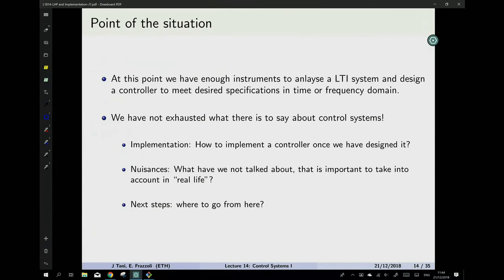But what's going on from now? Well, what are the next steps? First of all, we got to the point where we can come up with a control system, a dynamic compensator, which fundamentally is a transfer function. Complicated as you wish. After you did all your leads and lags, you just multiply, and you get a nasty transfer function. What do you do with that? Okay, good job, I got this mathematical function, and then how does that relate to the real world? How do I implement it?